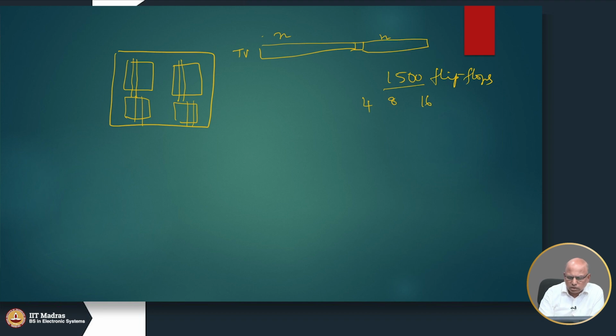So, there is what is known as automatic test equipment. I may have used this term before, automatic test equipment. This stores the test patterns. So, they may be scan test patterns. Remember what a scan test pattern will have to store. We have to store 2n bits, at least 2n bits.